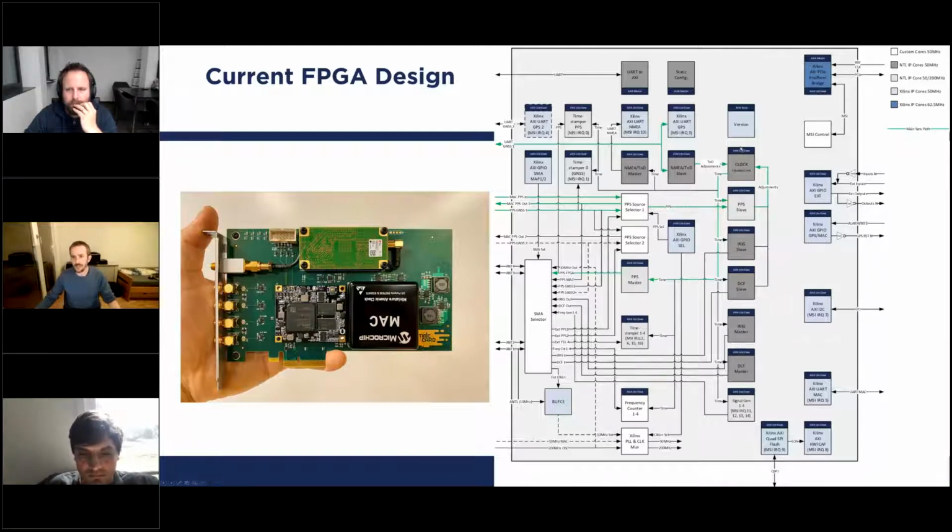The adjustable clock is responsible to maintain the time of the whole system. So this clock also provides the time to many other cores, which is then used, for example, for timestampers. The adjustable clock provides the time, but here only one main part is highlighted in green, the one which is going to the PPS master. This signal is then used to feed out to an SMA connector and can, for example, be used to synchronize the network card.